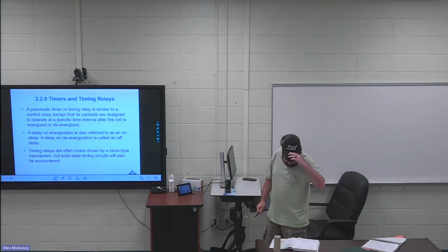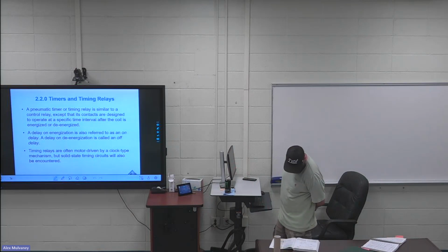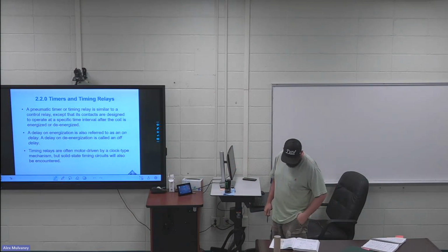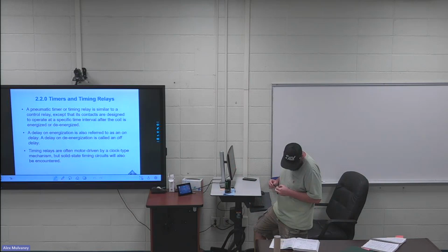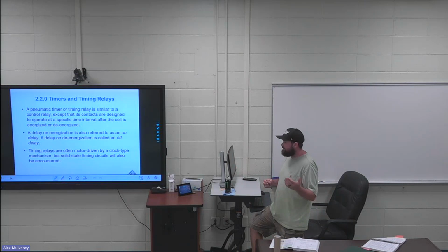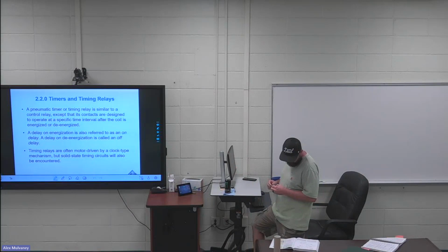On the right hand side of page 11, that first full paragraph or second paragraph of the section, the first sentence is my first like 5 lines. A time function is useful in applications such as lubricating systems of large industrial machines, in which a small oil pump must deliver lubricant to bearings of the main motor for a set period of time before the main motor starts. Next, the rest of that paragraph is a separate highlight. Furnaces also incorporate fan on delays to avoid blowing cold air into space whenever the system starts up.